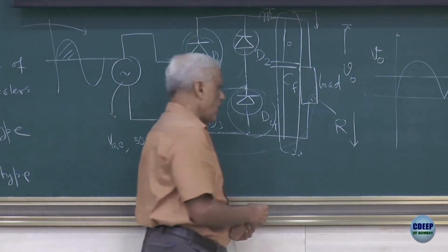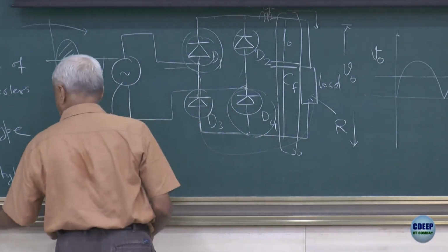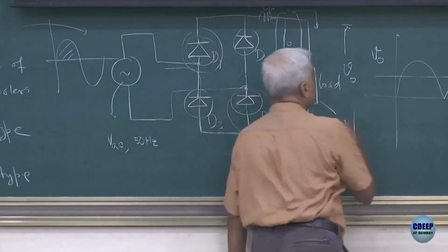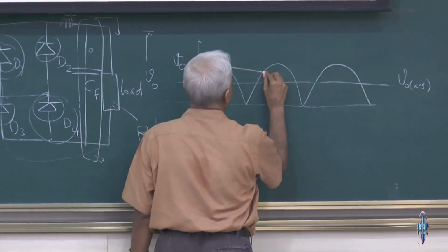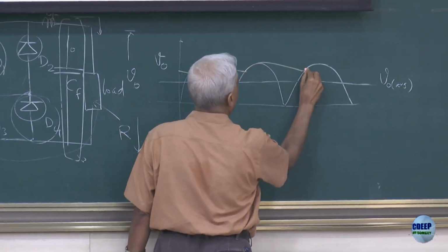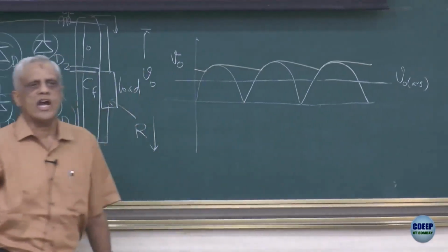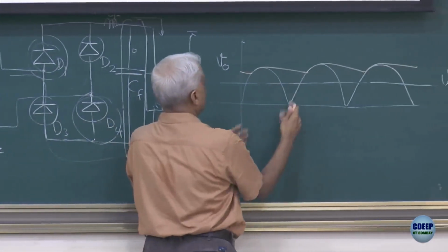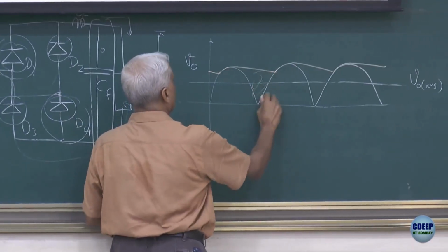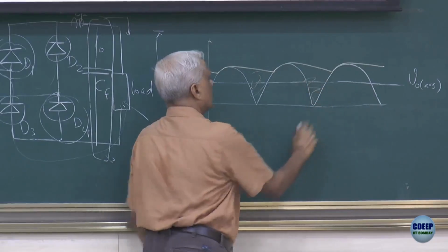But the overall effect of this would be that now, with this capacitor coming in, you will have this kind of output voltage envelope that you will get. So basically it will remove these valleys and peaks here. All these things, they are removed.